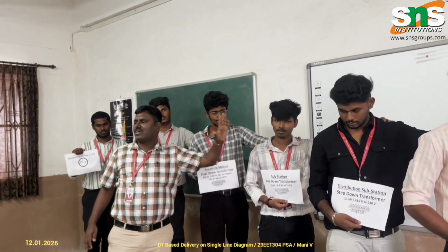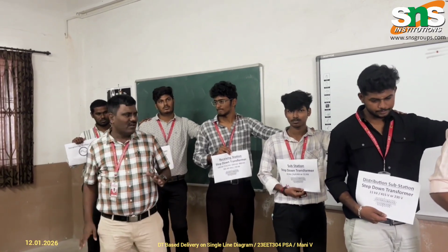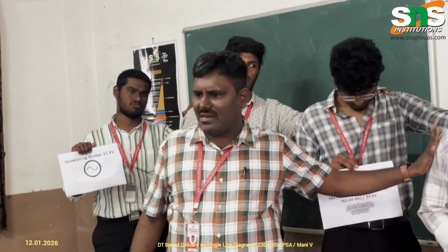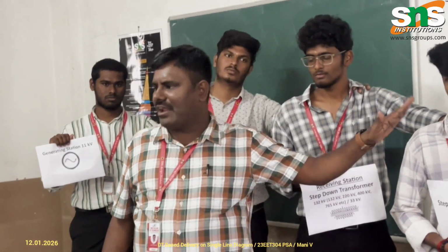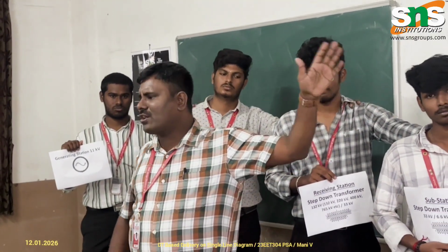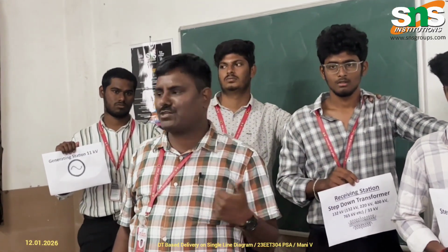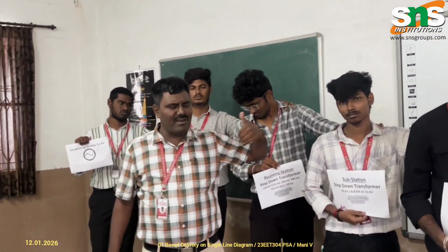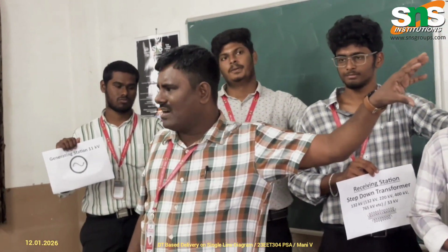The substations are located in areas like Coimbatore, Erode, Tirupur. The substation receives the voltage of 33 or 66 kV. Again, the 33 or 66 kV is converted into 6.6 kV, 11 kV or 22 kV, based on the load. A major industry expects 11 kV, 22 kV or 6.6 kV, which is given directly to the huge bulk load of an industry or factory.